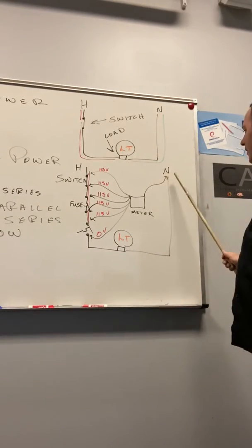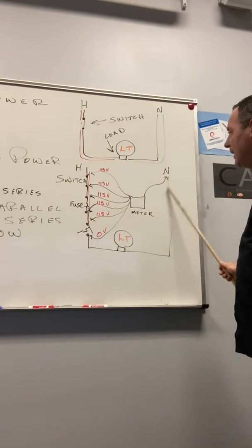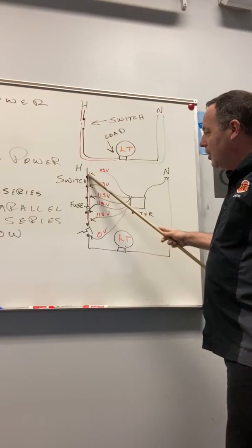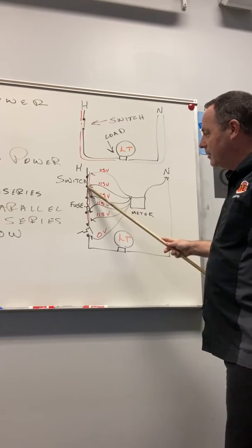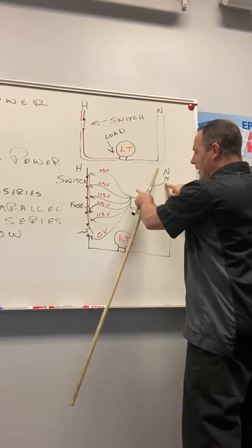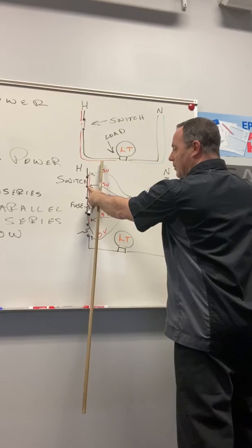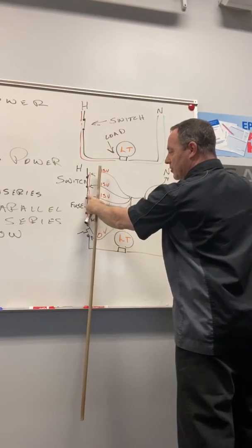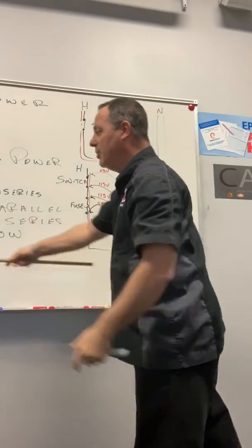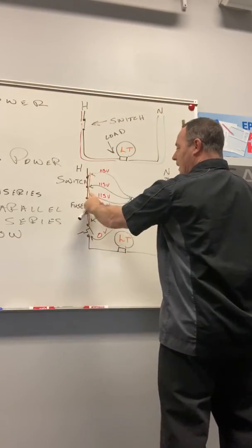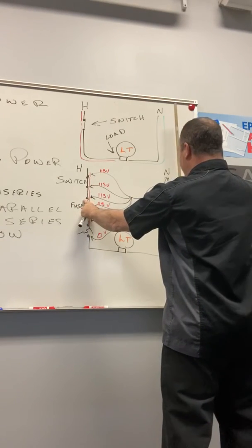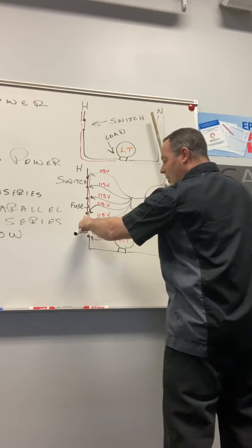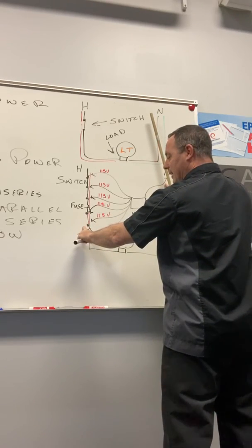1 meter lead right here, and the other one on solder hot, we get 115 volts. Notice the switch is closed. So if I took this one and this one, I'd read 115 because it's a continuous path. If I went to the next along that path, remember, as long as you got a path, current will flow. Here's my power supply, my path, here's 115. Across the fuse, 115. Continue down the path, 115.